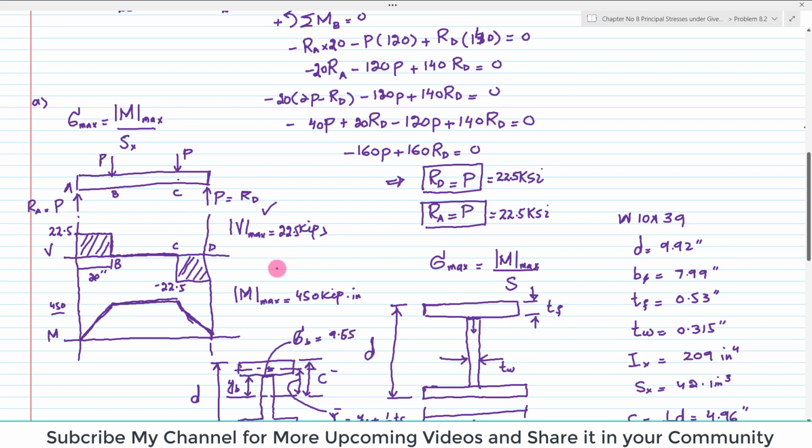Clear? You have this value, you do not have SX. So from the W10 by 39, if you go to appendix C of the book Mechanics of Materials by Beer and Johnston, you will find the properties of this rolled steel. So from that you can get the height of the beam, the breadth of the flange, clear, the thickness of the flange, the thickness of web, the second moment of inertia, section modulus.